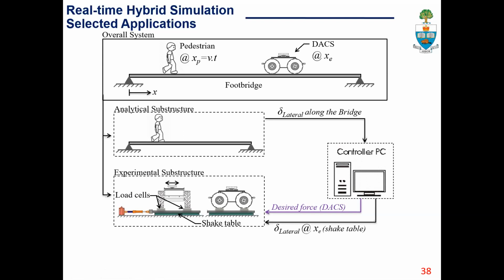First of all, this is an active device, so our controller needs to also compute the optimum control force, and it should introduce it to the EMD so that we can introduce the control force at the bridge, at the load cells. So that is a fact that comes with the active nature of this control device.